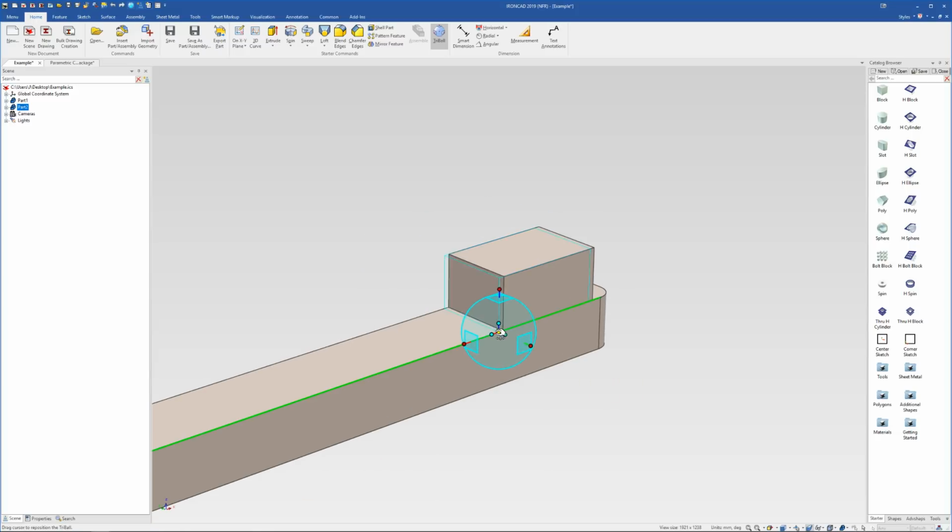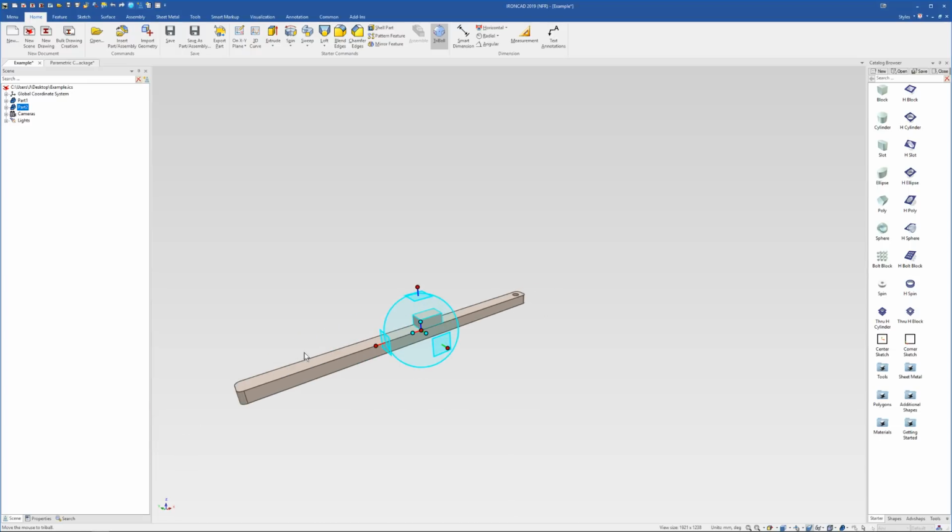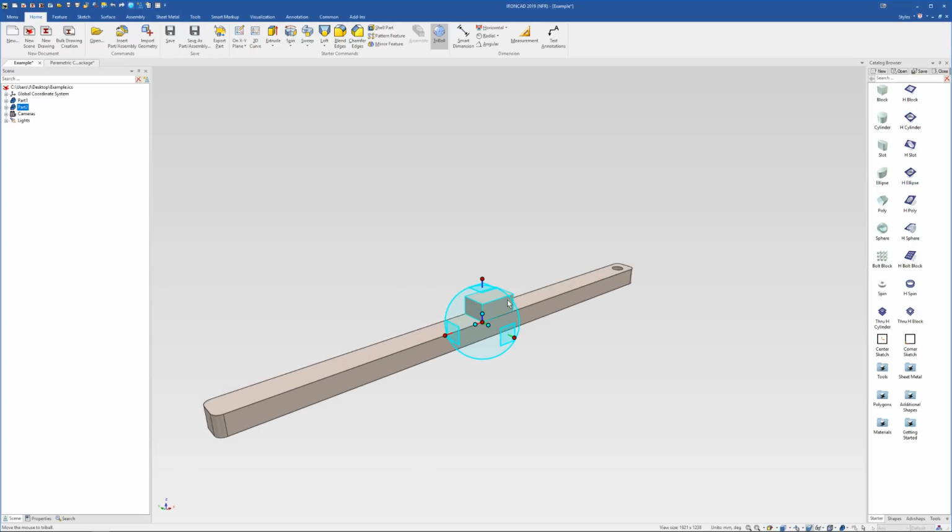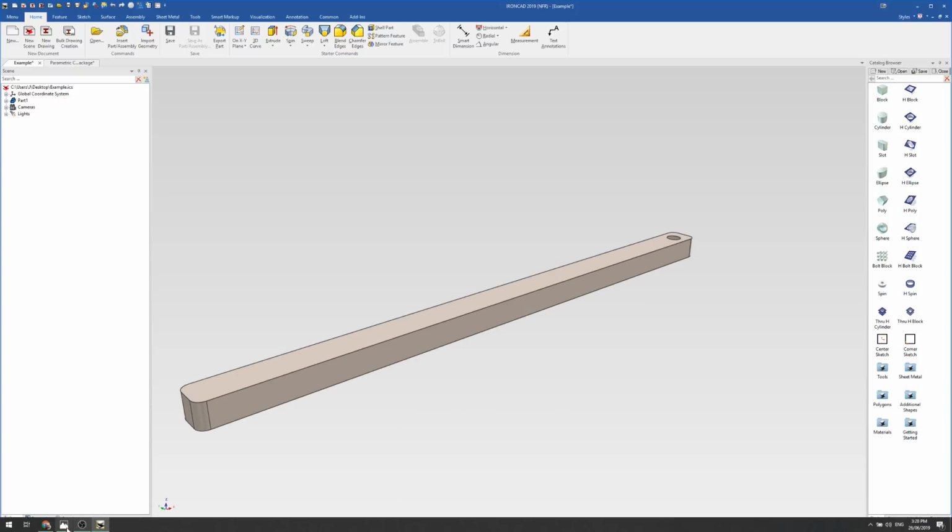So you can see here, I can be dragging, hold down the shift key once I'm past halfway here, and it's going to snap to midpoint. I can just let go now of my mouse and zoom out, and now I've got that at the midpoint. So those shift key snap points are really useful when you get used to activating them whilst you're modeling. Let's just move on to the next one here.